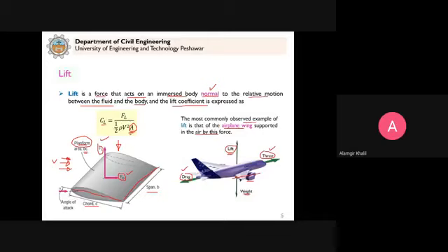Now in this figure, the other important thing is this chord here, you already know from mathematics what a chord is. So this chord, where we join these two points, makes an angle with the horizontal. Any point you draw horizontal, it makes this angle, and it is denoted by alpha, commonly in fluid mechanics books, and this is known as the angle of attack.